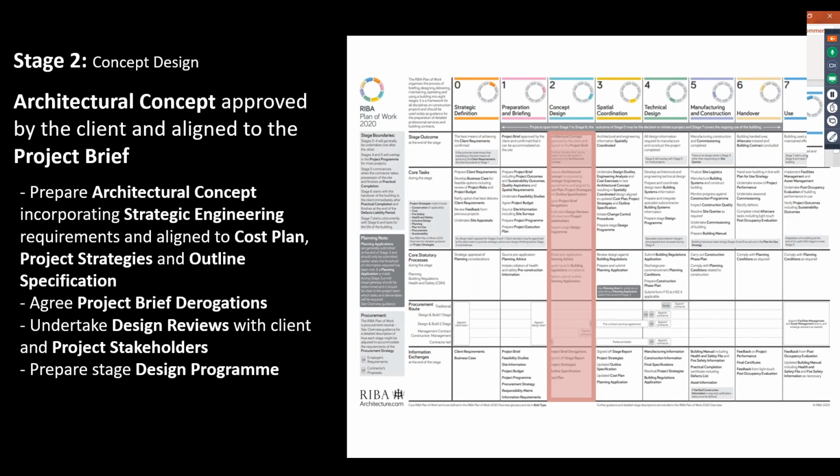And I think one of the points about the stage 2 and stage 3 boundary is there is not necessarily a right or wrong approach about how many tasks need to be done. And let me give you a simple example. So for the core of an office building, stage 2 may or may not have detailed calculations for the staircases or for the toilet numbers, or maybe it does. This is all something that needs to be agreed between the design team and the client team in terms of how much information is needed to produce a robust concept design.